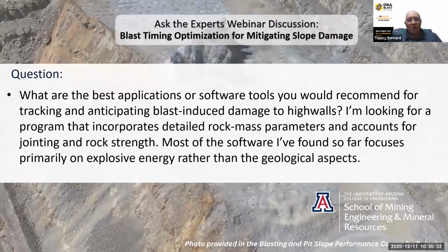This is based on the rock mass parameters, basically using the UCS, the UTS, the P-wave velocity, and the density of the rock mass. So this is working well. And if you have a map of your rock mass with different parameters, then it can give you different critical PPV not to overpass in different areas, and you can then design your timing based on that.